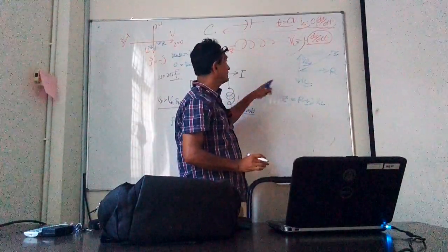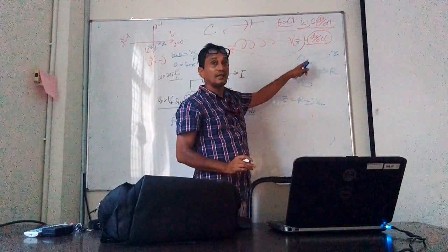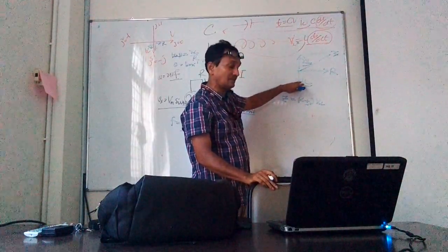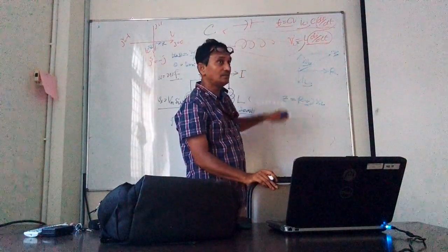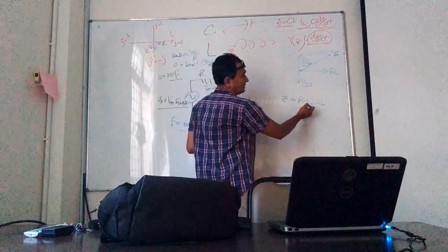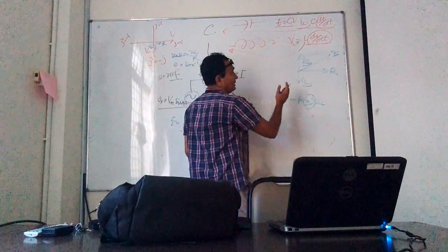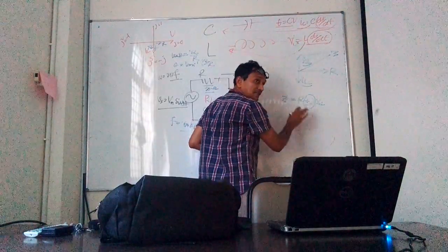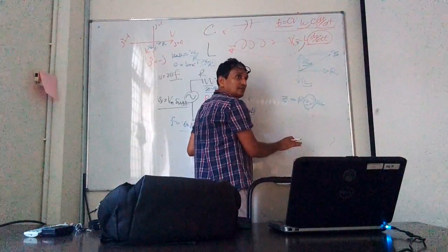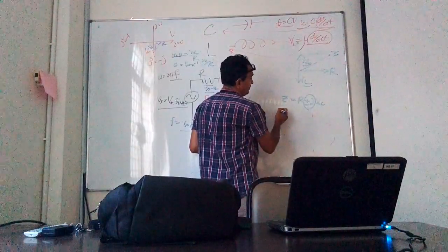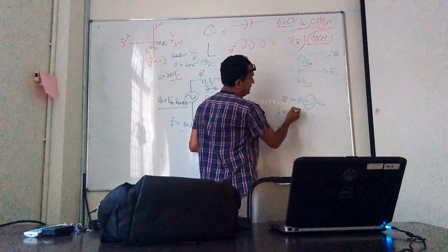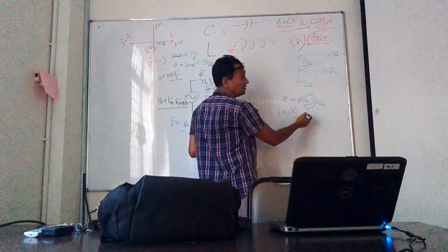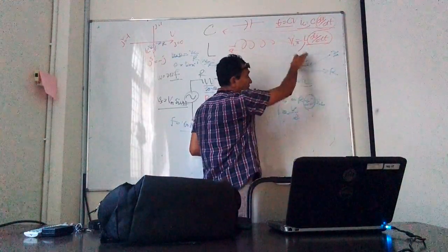The XL circuit, this should be the direction. Sorry, I forgot to analyze either XL or IL itself. Once you write this is positive, that means it is actually positive direction, 90 degrees leading. Impedance leading, current lagging, because the current is nothing but voltage by impedance. So impedance leading means current will be lagging. Current should be downward.